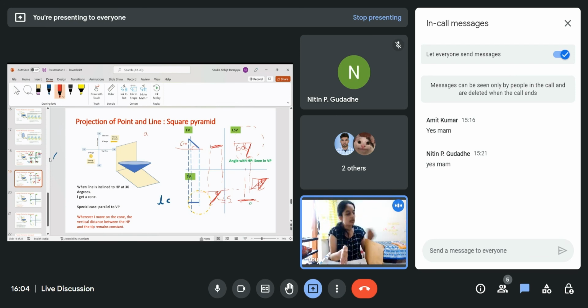I'm telling you that this is a line. Where's my pencil? Yeah. So this is a line. I'm rotating it by 45 and then by 60. Okay. So here, since I rotated it by 45 here, I see the true length here, and then nowhere can I see the true length later once I rotate it by 60. In this view, I cannot see the true length at all.